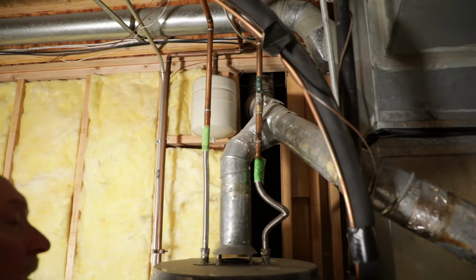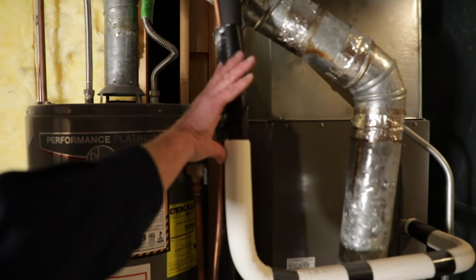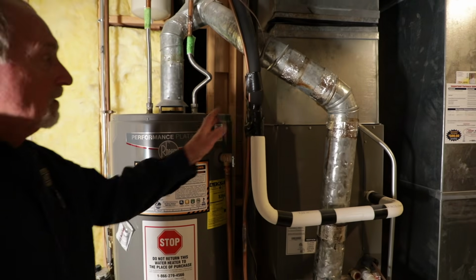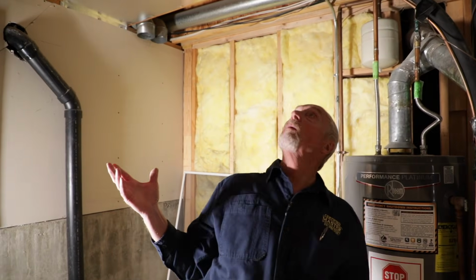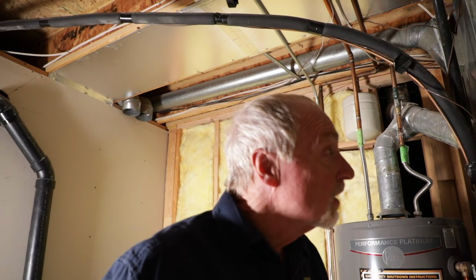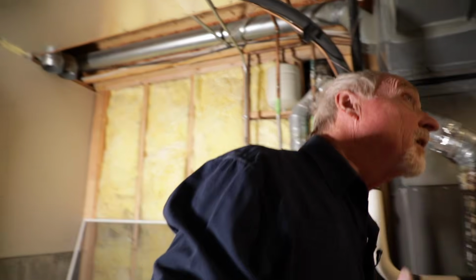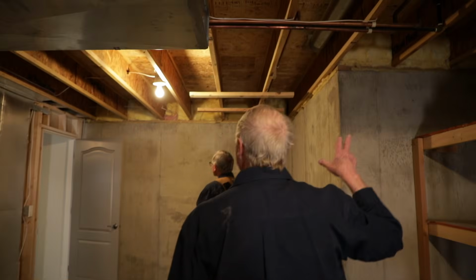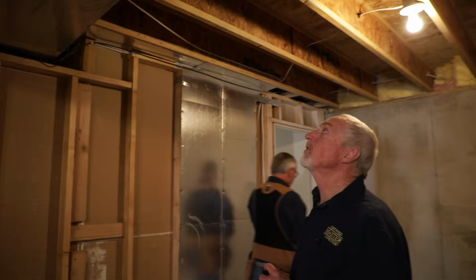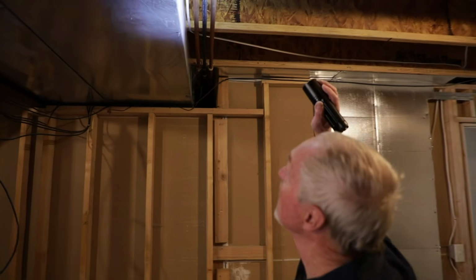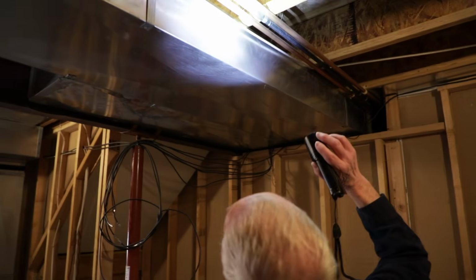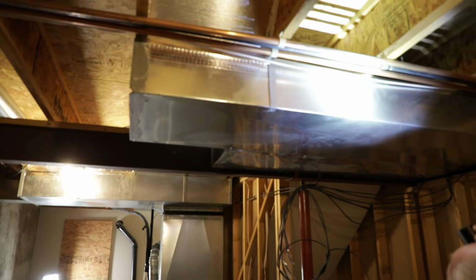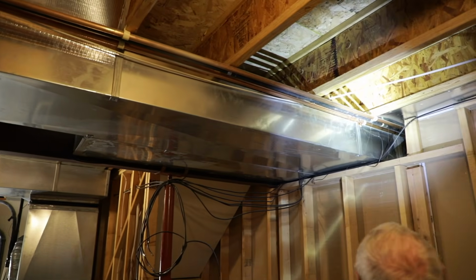We earlier had comments with Ray about the refrigerant line not touching the gas line here, which would be something we would like to keep separated. And so what we're looking at here, frankly, looks pretty good. We will continue walking around here, looking at our copper, looking for evidence of leakage, checking our gas line. We want to see copper strapped with copper. Here they used a steel strap on the gas line, which is fine, and then they used plastic straps for the copper, which is perfect, so they did this correctly here, so we're very happy with that.